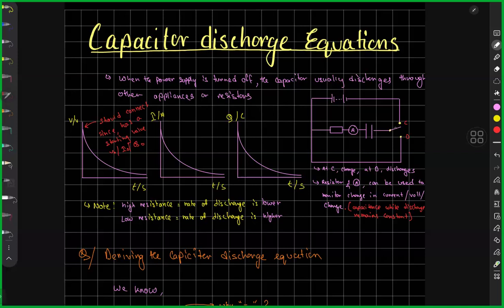And when connected to C, it is a typical DC circuit with a power supply here, a resistor here, an ammeter measuring current, and the capacitor being charged and discharged. So when it's connected to C, the capacitor gets charged up. And after a point, when it's completely charged, current stops flowing, even though it is connected to C over here. Okay, so current stops flowing in that case, and we have a fully charged capacitor.